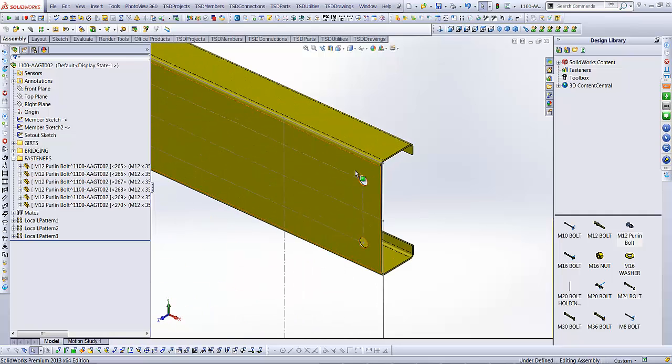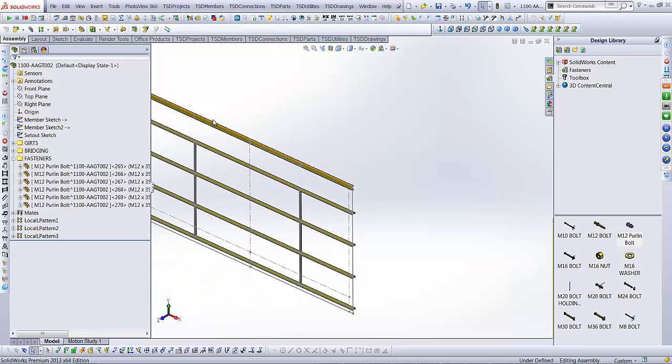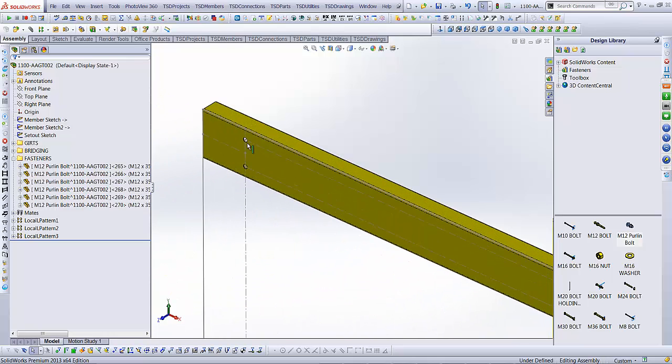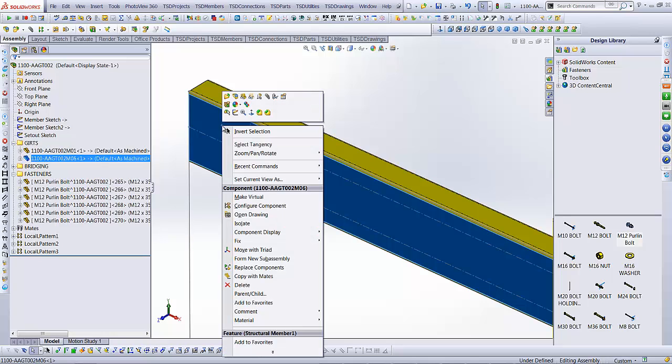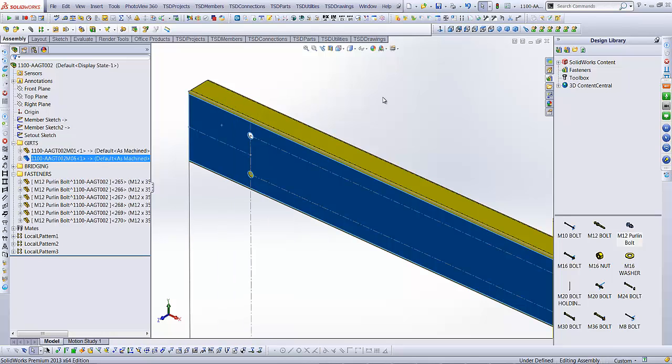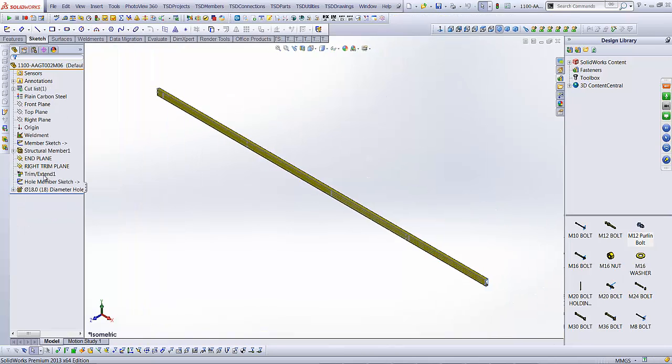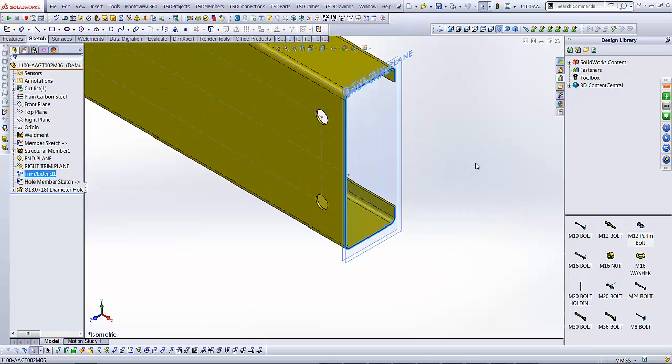Now with the fascia, we've got to do a little bit more work around this because the fascia itself has got holes in the end, and we've got holes over here that seem to be lining up. We need to move those over so that they're stock standard 35 at this end. Okay, so we're just going to go in and modify this fascia. Now we need to check to see if there's any trims. There is one at this end that we need to take away.